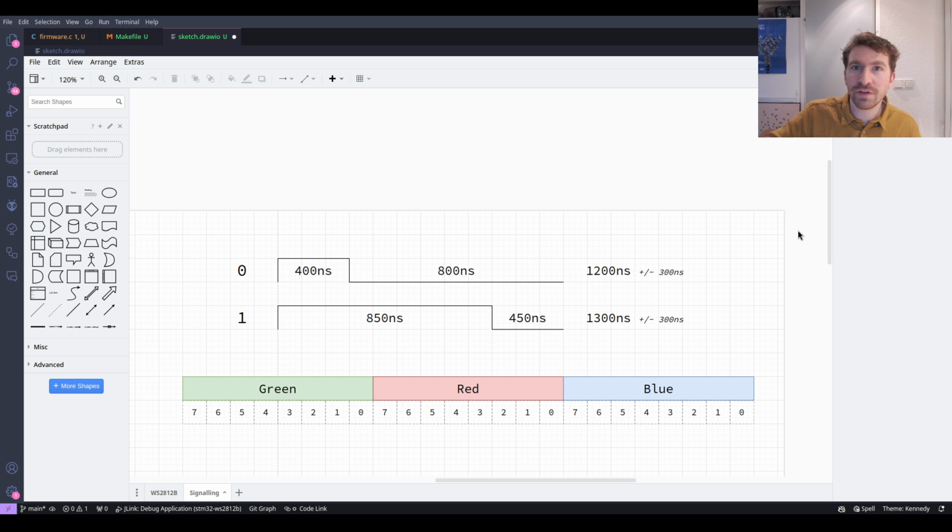It's sort of like a shift register. The first pixel, if you send in the data, it will take that, it will say, this is my data. And then the next time you send it data, it will go, oh, this is actually for the next one, so I'm going to send it along. And it will just pass the signal to the next pixel. And of course, when you start sending it data for the third one, it will say, oh, this one's not for me. It will pass it on. The second one will say, oh, this is not for me. It will pass it on. And that's how you cascade the signal downstream.